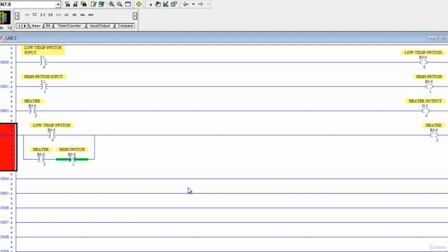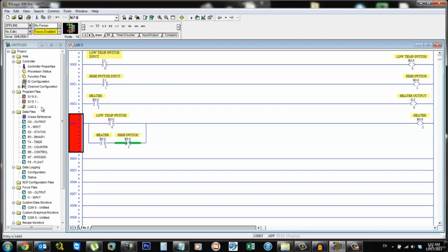Now we're going to assume that maintaining temperature within a certain range isn't good enough for a particular process. Now we want to maintain temperature at a specific set point rather than, let's say, between 80 and 90 degrees. We want to be able to set that temperature at 82 degrees and the temperature stay there all the time. So now we're going to get rid of our digital controls and we're going to replace them with analog, and we're going to use a PID control.